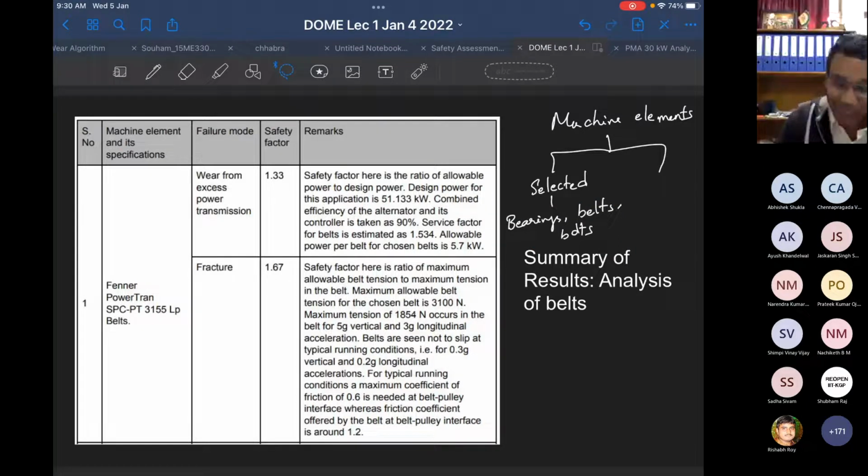Every manufacturer, let's say a bearings manufacturer, would have a wide variety of bearings which they make, and under each variety, let us say cylindrical roller bearings, they would have a lot of different models, and for each model they would provide some product specification. By looking at these product specifications, you have to select the appropriate component for your application. So some elements will have to be selected.